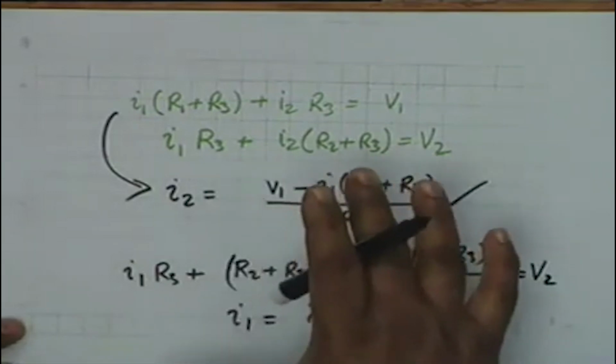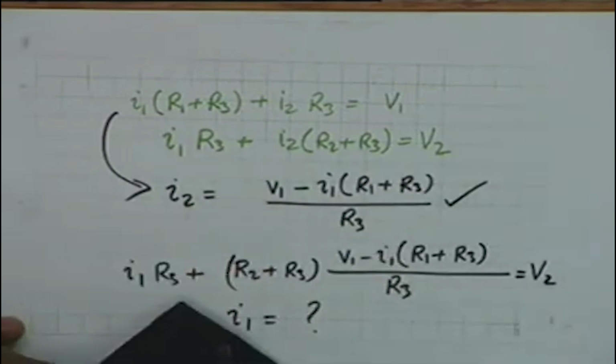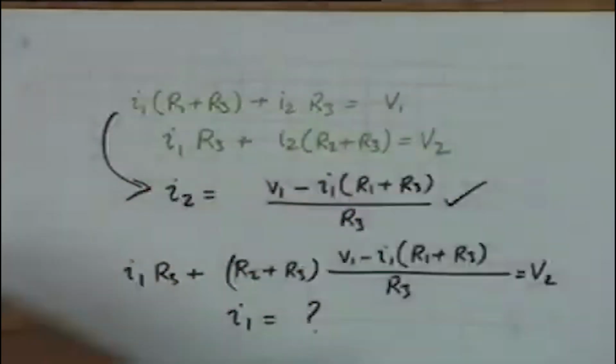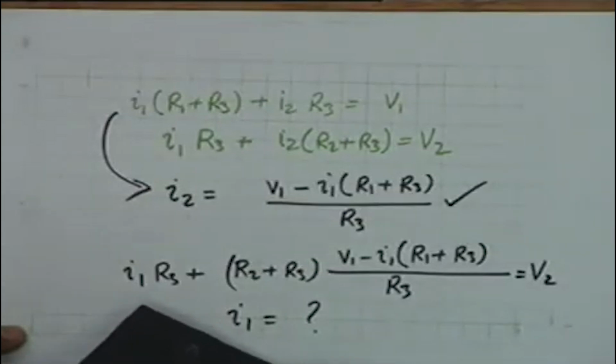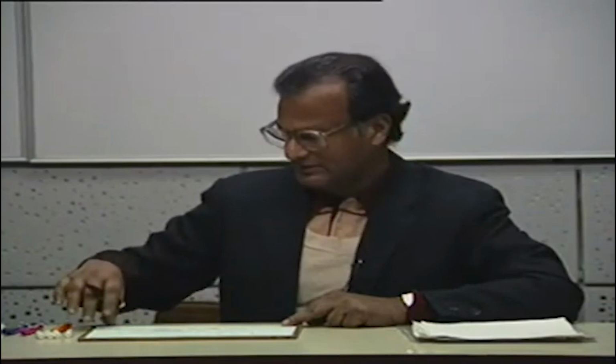However, if you have more than two loops, let us say you have 50 loops, a power system network in which there are 50 domestic consumptions, and therefore there are 50 loops, then the method of elimination becomes extremely troublesome and tedious, and therefore you need an alternative and a simpler method, and this simpler method is offered by the so called method of matrix equation solution.